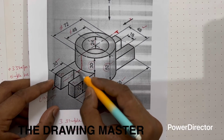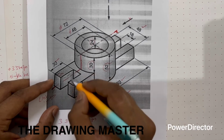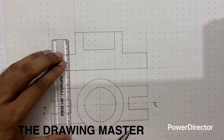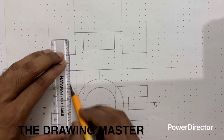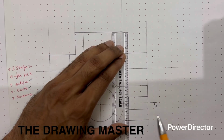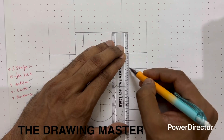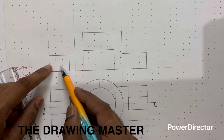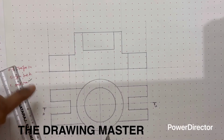When you will cut this object, it will be sectioned from here. So this surface will be untouched. This will not come in cutting plane. So take the projection from here. You can see this. Here also we'll take the projection. So now in this area there will be no hatching. Here also there is no hatching. So in remaining area we have to do the hatching.